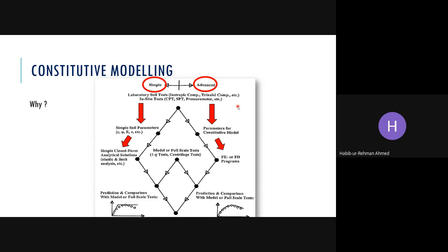Okay, so these will never be used, and they cannot be used. These type of advanced models and their subsequent parameters cannot be used in closed form solutions. Okay, so we have a split up. The closed form solutions I've shown you, and I have given you a flavor of the understanding of a constitutive model for general materials like Mohr-Coulomb, Drucker-Prager, etc., and the vision of a 3-dimensional constitutive surface for the soils, like the Cam-clay model.